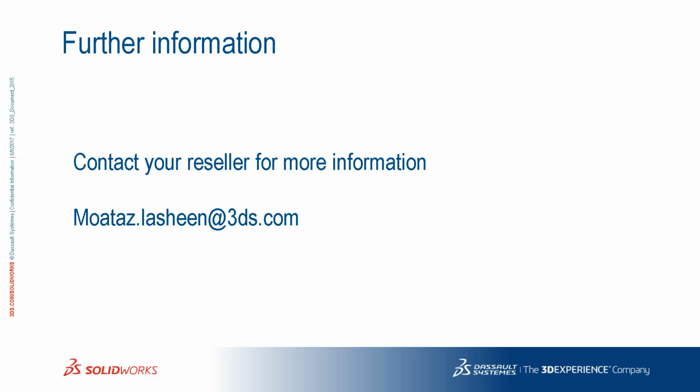I can see one question here. What's the difference between 2D and 3D? So yeah, very good question. One of the users is asking, in the meshing we have two types, 2D and 3D. Of course, by default, Flow Simulation uses 3D meshing. However, in some cases, when you have a symmetry in your parameters, you can specify a two-dimension mesh.